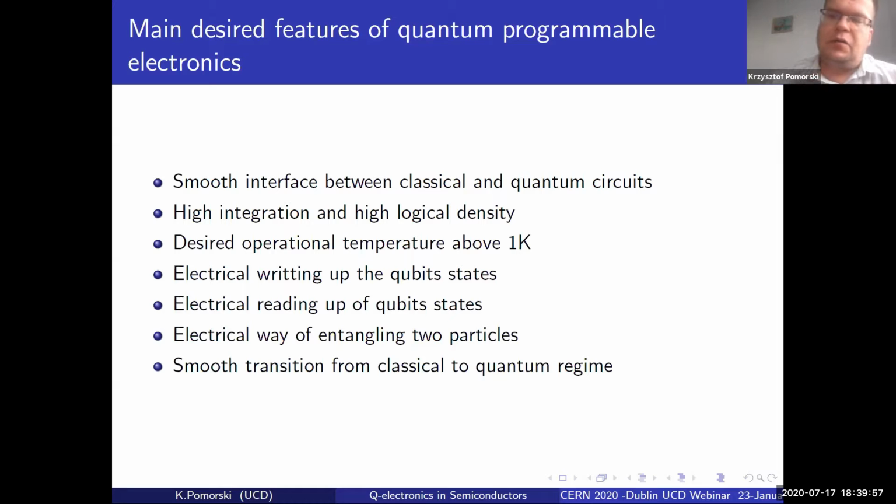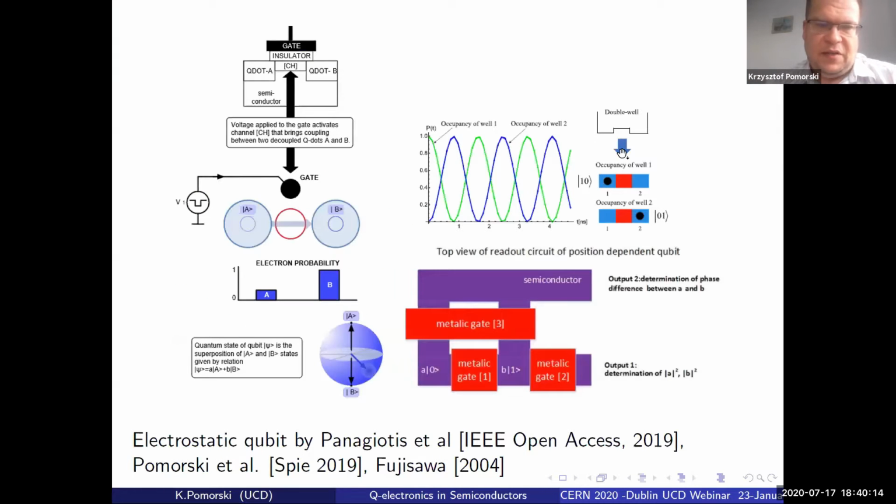Because of those obstacles, there is some saturation of possible progress in superconducting electronics, and there is a nice alternative, which is to use coupled quantum dots. The idea is that you go to CMOS technology, where you have a source and drain, and a gate on the top, and you can control the connectivity of source and drain by the voltage applied to this gate.